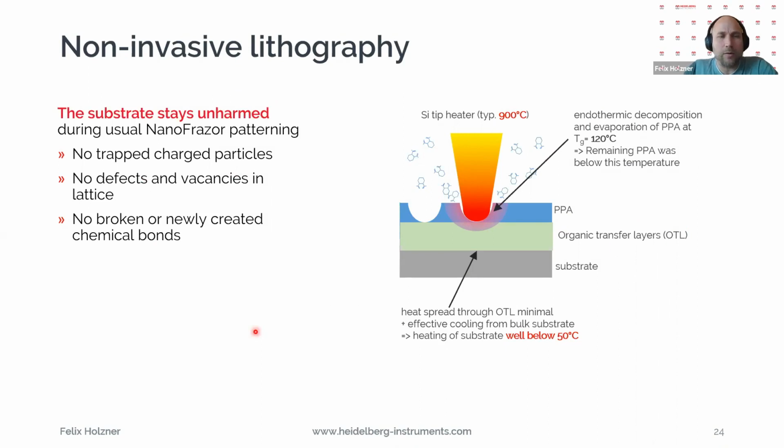So it's not only about charging an insulating layer, which in general can be an issue with non-conducting surfaces or layers for e-beam lithography, for example. It's also that, in e-beam lithography, most of your energy is deposited actually in your substrate and can create, depending on your substrate, some damages, like you can get some vacancy, lattice defects, or you create new bonds between your resist, for example, and your top material. So you can have some damages.